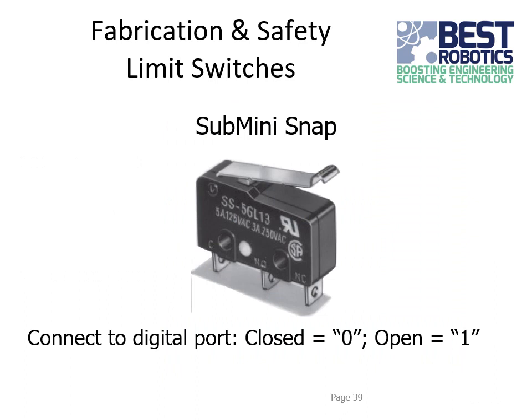Here's another nifty little component called a limit switch. These are just little switches that you can have your code read as a 1 or 0, depending on whether it's pushed or not pushed. And this can be a way to have software controlled limits on how far an arm can rotate, or to tell if your robot has bumped up into something that you might not be able to see from the spotter's box or the driver's box.